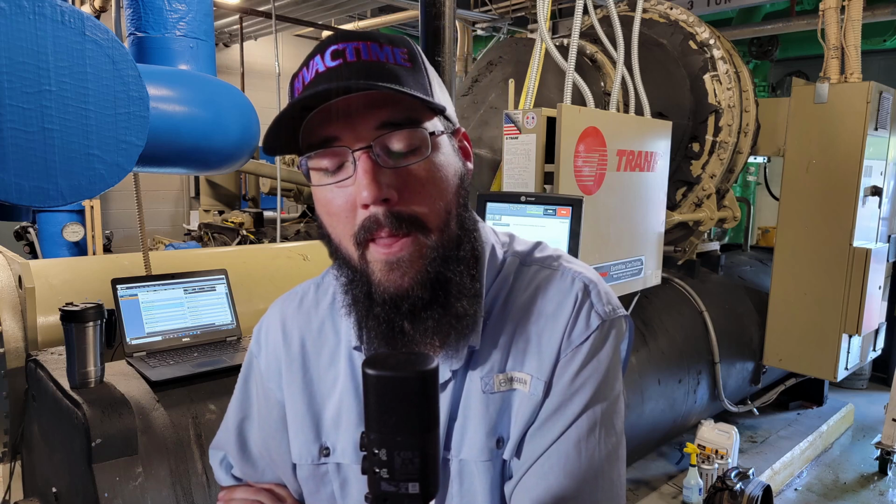Yeah, no, this is it. This is how we're using eductors. This is how we process oil recovery inside of a chiller, whether it be air cooled, water cooled, screw, centrifugal. You don't see this kind of stuff with, say, reciprocating or scrolls because we don't typically use these types of evaporators with those. Just with a screw or a centrifugal, we use evaporators that need these recovery systems in place for it to function properly.